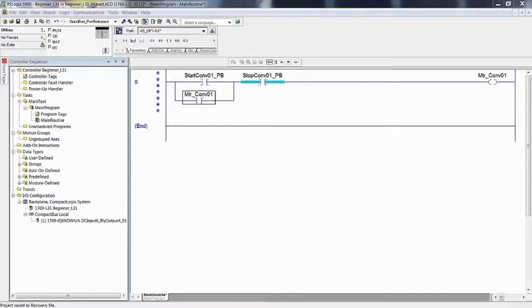If that is not already done. If it's already done, well, then you're stuck with it somewhat. Either way, you're better off writing your program without assigning I/O and then go back and alias it to actual I/O. Either way, it's going to work out better for you.